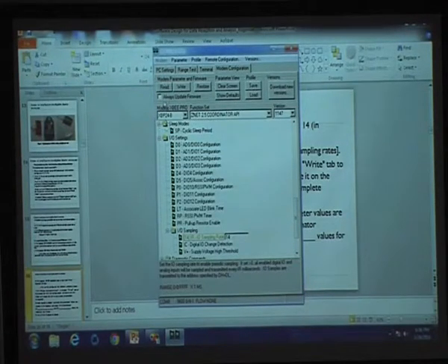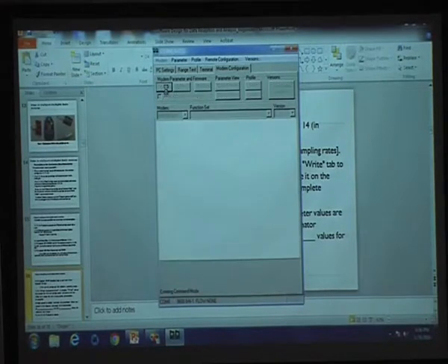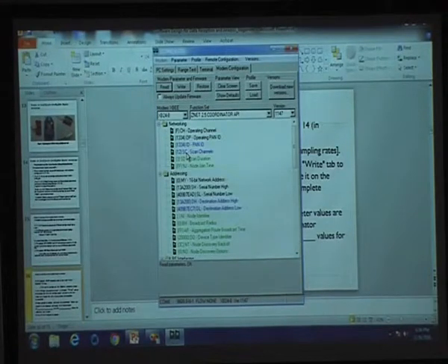Now if you see, once I click the read button again, it shows me all the values which exist over here. The PAN ID has been set to 1234, the scan channels has been set to 12, and the destination address high and destination address low of this particular radio communication module, the serial address high and serial address low of this, become the destination address high and destination address low of that particular receiving coordinator. So those values have been set here.